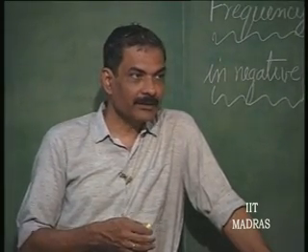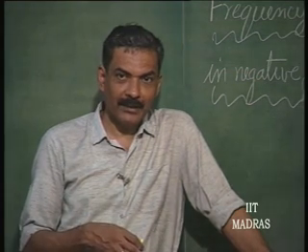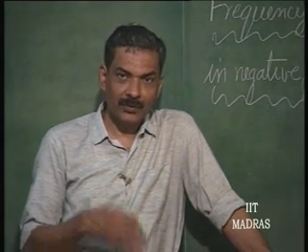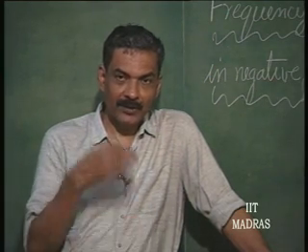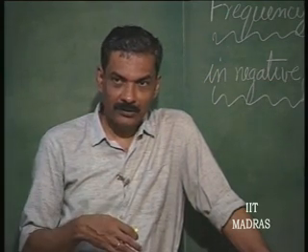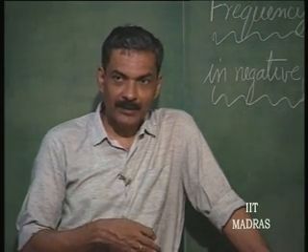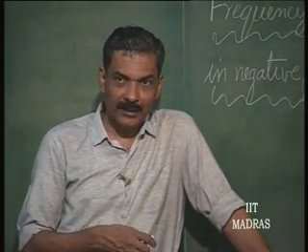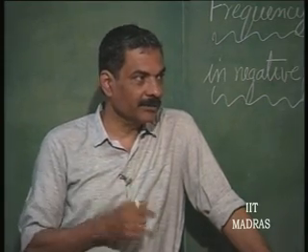Positive feedback with regenerative action is adopted in order to make the circuit work only at two levels at the output. It is a nonlinear function. It is going to be at high or low, depending upon whether the input is increasing or decreasing, and that is a memory element, and therefore, we have discussed that as a separate application.